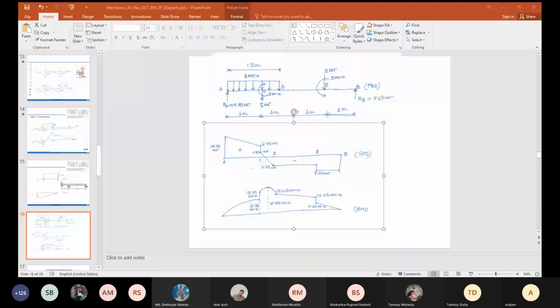Sir, I also see sometimes there is a discontinuity at a load point and sometimes continuity. What sometimes there is? The value at points are same, left hand here and right hand here. Theoretically, this is not correct. This line should be dotted line. And this 6.75 kilonewton is at C minus delta, 1.75 is at C plus delta, where delta is very small but not zero.